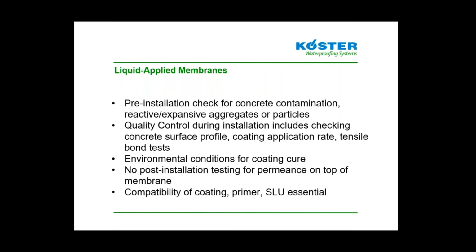The reason also it's important to perform so many field quality control installations during the actual application of the material, including checking the wet thickness of the material and the coverage of the material. The question is asked whether post-installation testing can be performed to certify or to demonstrate the performance of the liquid applied moisture mitigation membrane. At this time, no such tests are available because high moisture conditions may exist deep in the concrete, not close to the applied membrane in the top surface of the concrete.